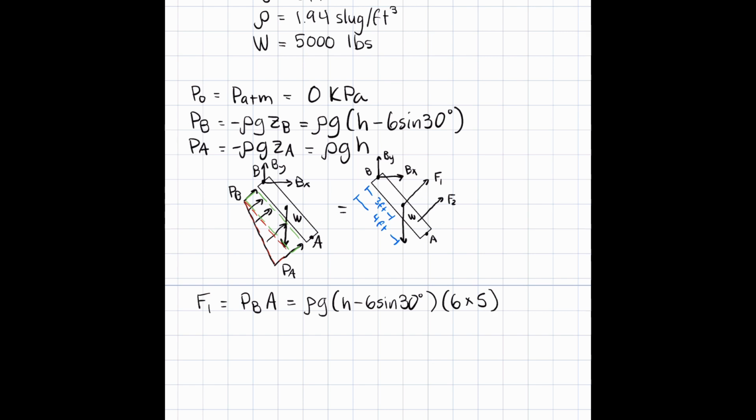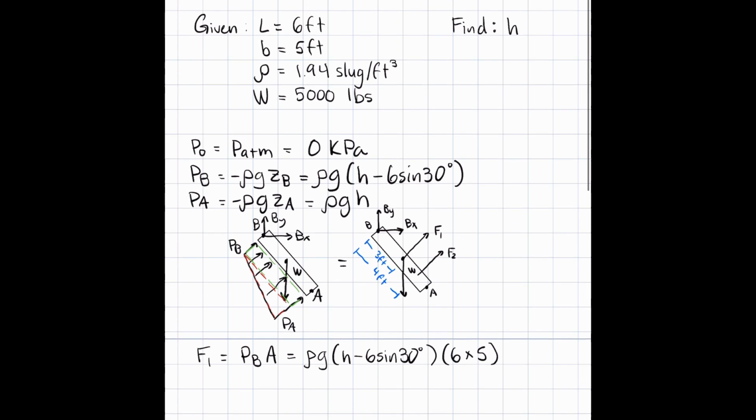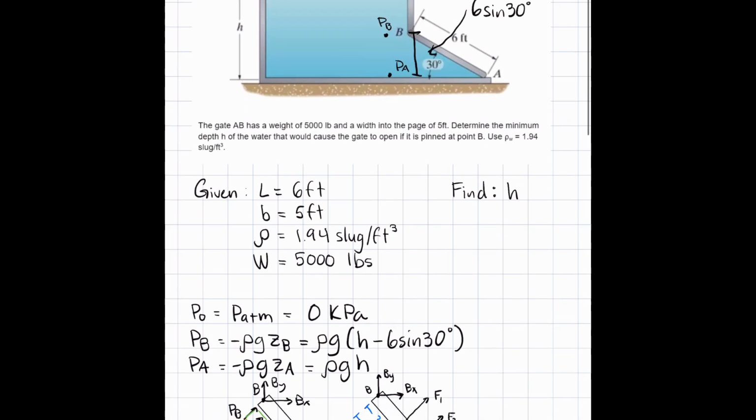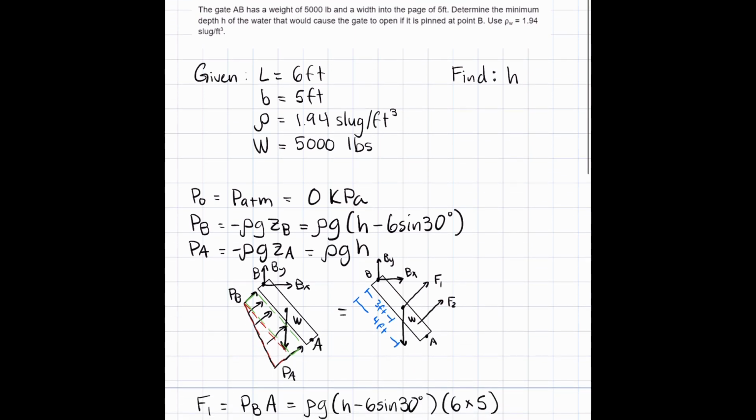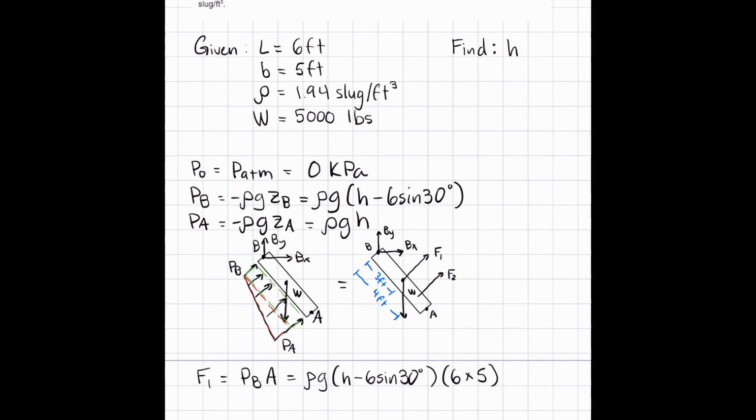And I'm neglecting the units in this problem and writing out the answer here for the most part because everything is in standard imperial units. You know, there's no crazy conversions we're going to have to work with. The only thing to keep in mind is that weight as 500 pounds is already a unit of force, so we don't have to multiply it by gravity. But everything else is consistently in feet, pounds, etc.